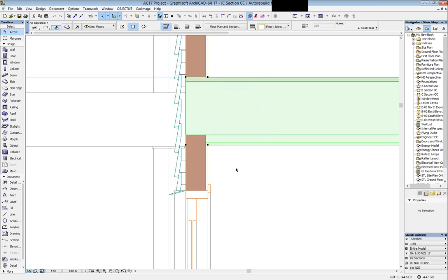And if you don't want to do it in a modeled fashion, you could go back to using the very cool CADimage detail element tool, which has wall frames and floor framing and rafters and all that kind of 2D overlay. But if you want to keep it 3D, you might want to think about using complex profiles, or CADimage wall frames, and it keeps it all modeled. At the end of the day, we're trying to keep everything modeled as much as possible. So choose your weapon in that case. Do I want to do it in 3D, or do I want to do it with 2D overlays?